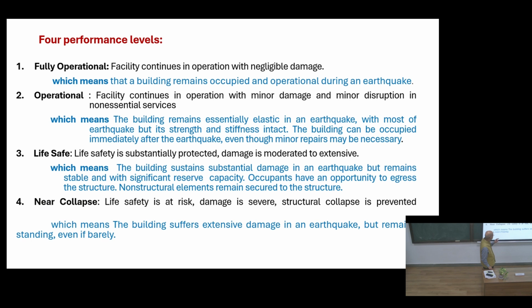It means the building suffers extensive damage in the earthquake but remains standing, even barely. That means it may fall in a month, 15 days, 20 days, but it gives sufficient warning to us. Meantime, you can evacuate the people, you can save important things, machines or many other things, you can take them out of the building. So that much time is available to you. That is how you measure the performance.